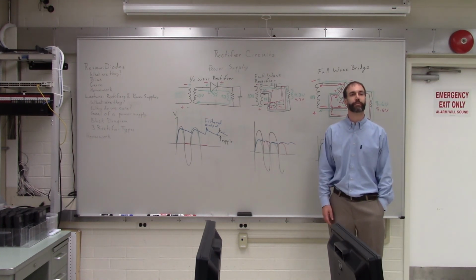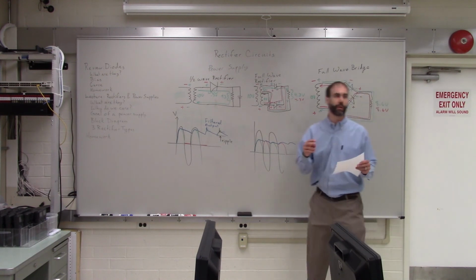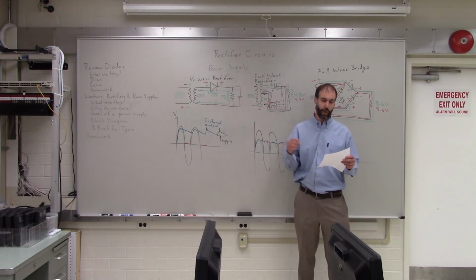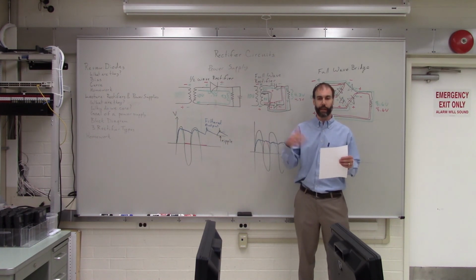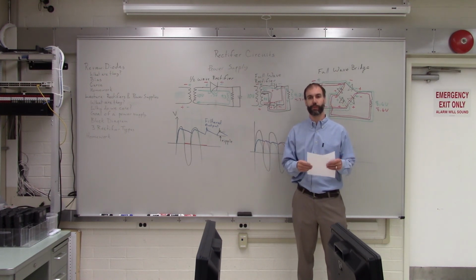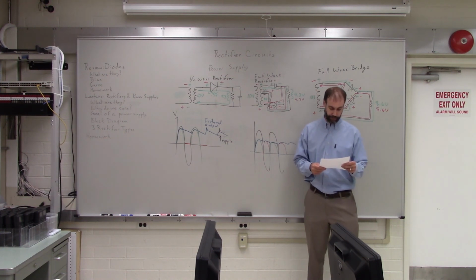They need transformers, right? Yes, that's right. There's a couple of notes about the transformers. The transformers actually have circuit breakers on the backs of them. So you want to make sure that those circuit breakers are pressed in. That way the electricity will be flowing. If you hear it click, that means one of them blew. That means something's wrong with your circuit. So turn everything off, check your circuit, figure out what's going on, and then wait for about a minute. You'll hear another quieter click, and then you can push the circuit breaker back in and turn the transformer back on.